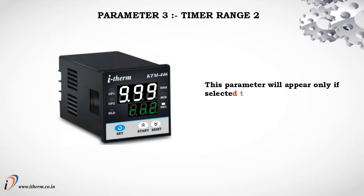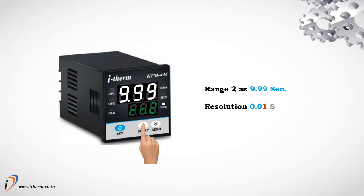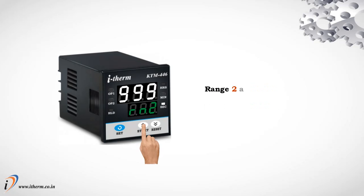Parameter 3. Timer range 2. This parameter will appear only if the timer function is selected as cycle 1, cycle 2, or cycle 3. It sets the timing range and resolution for parameter set time 2. Range 2 as 9.99 seconds, resolution 0.01 seconds. Range 2 as 99.9 seconds, resolution 0.1 seconds. Range 2 as 999 seconds, resolution 1 second.